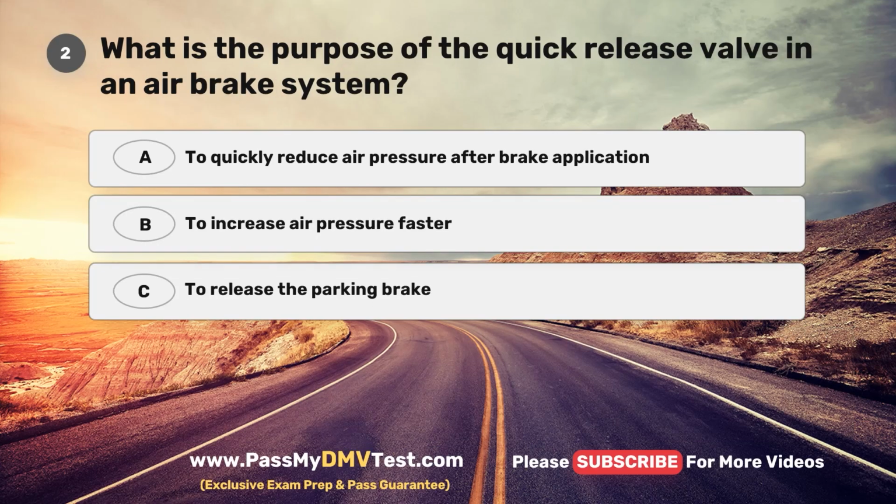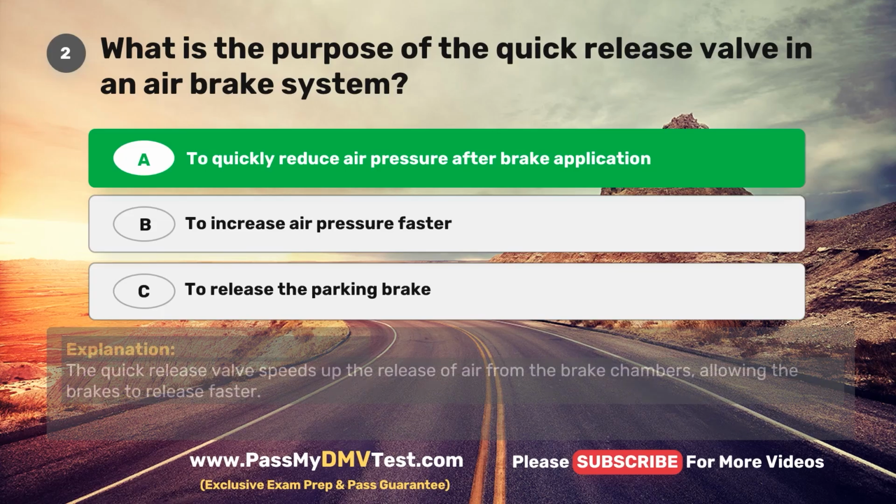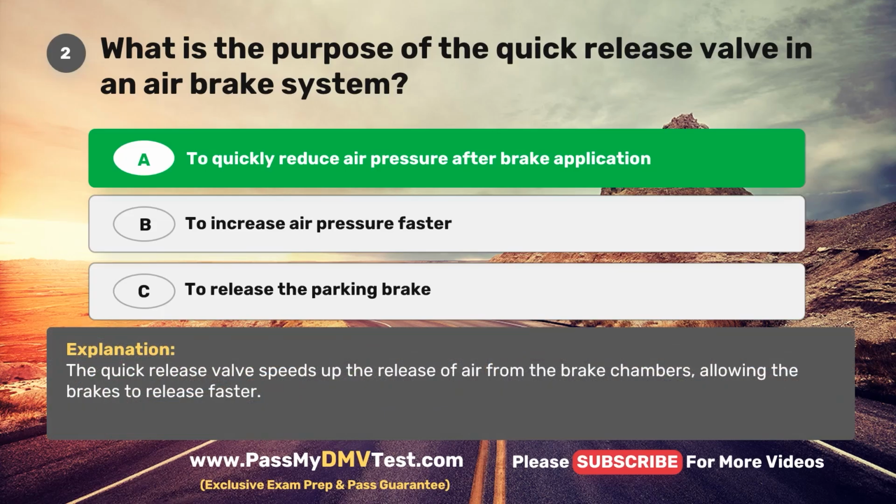Question 2. What is the purpose of the quick-release valve in an air brake system? A. To quickly reduce air pressure after brake application. B. To increase air pressure faster. C. To release the parking brake. The correct answer is A. To quickly reduce air pressure after brake application. The quick-release valve speeds up the release of air from the brake chambers, allowing the brakes to release faster.